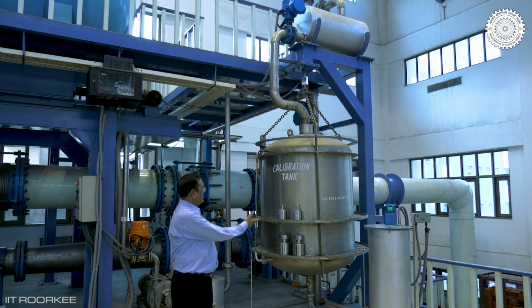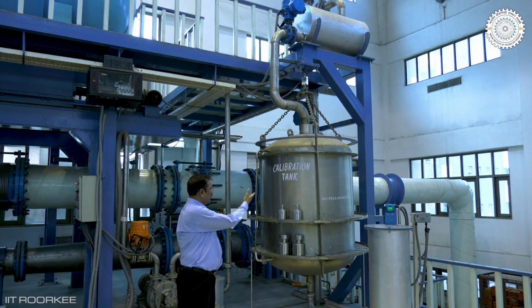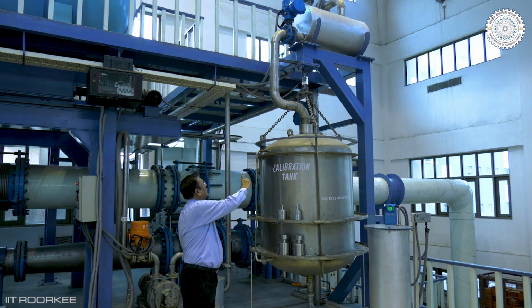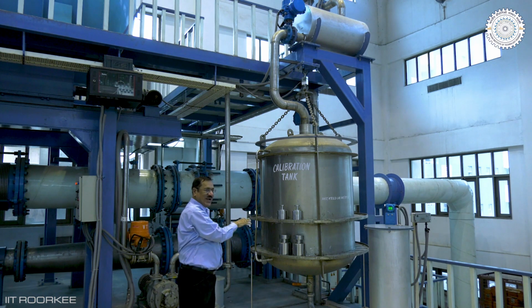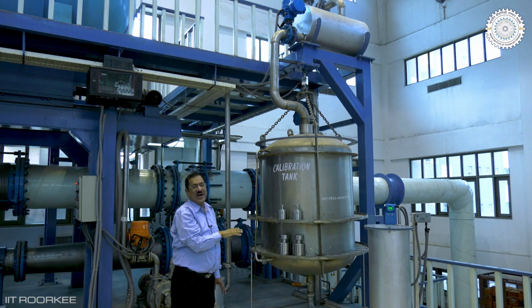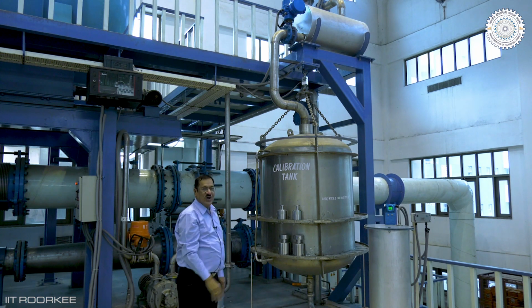Here we can see the calibration tank which is used for calibration of the main measuring tank which is 45 tons. We can see that we have got weights by which we calibrate this tank of 2-ton load cell, where you can see a load cell at the top which is a tension type load cell. We calibrate this first by actual dead weights which are calibrated by the accredited laboratories, and then this tank is used for calibration of the main measuring tank.